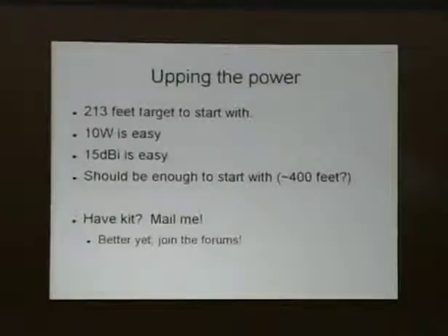I'm also looking to start increasing power levels. 213 feet is my target to start with. 10 watts should be pretty easy to get hold of. 15 dBi of antenna should be pretty easy to get hold of. That should give me about 400 feet, which is enough to start off with. If you have any UHF equipment, or if you just have a potential source for obtaining it, then please get in touch. Even better, join the forums. Actually, contribute to this community that's building.